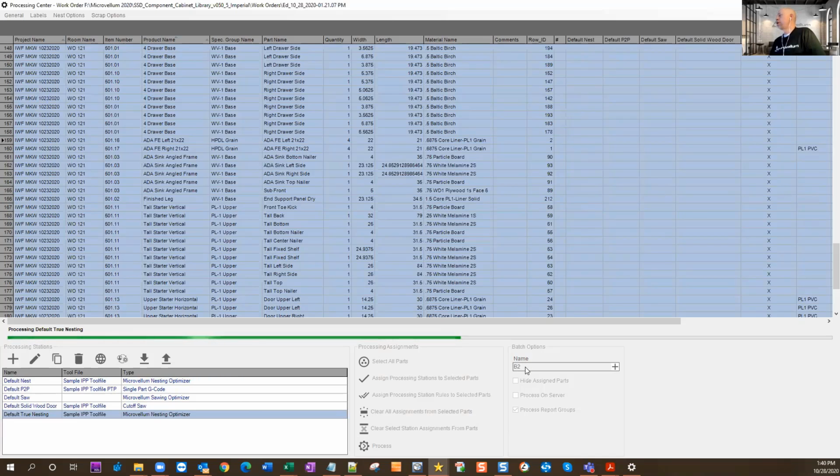And with the batch name, also realize spaces can also be an issue. I know a comment was made that it does feed into the machine name or the G code name. So if you would put in a space and have barcodes, you could run into some issues that way. So if you needed to place a space, you would actually use the underscore symbol. So technically it's not a space per se. It would be another character.